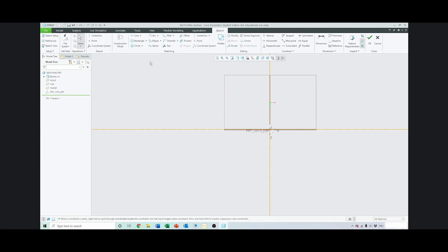Okay, so the next tool on the rectangle drop-down list is the slanted rectangle. Very simply, the first place you click with this tool, you'll start to create a line. Click again to set that line, and the rectangle will form as a projection from that line. You can then dimension this rectangle however you wish by either double-clicking on the pre-made dimensions or selecting the dimension tool and using this to create your own dimensions.